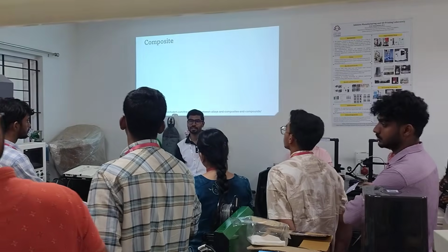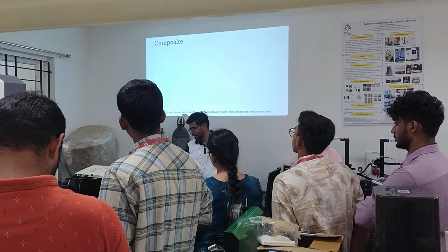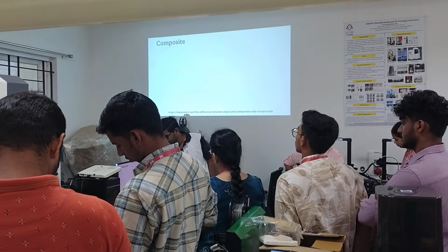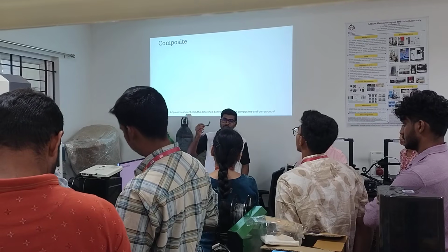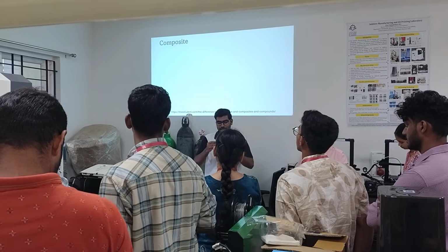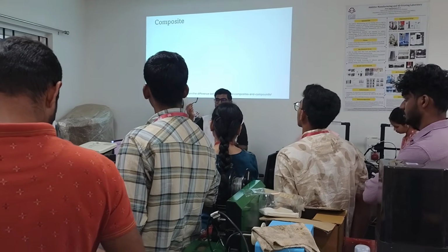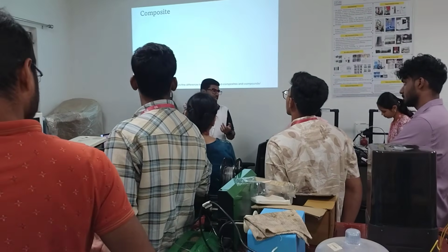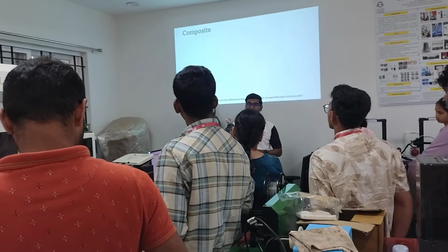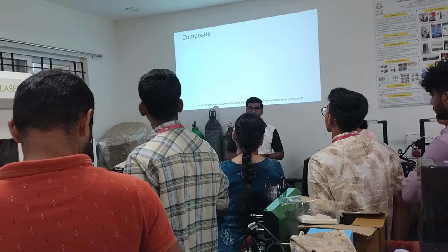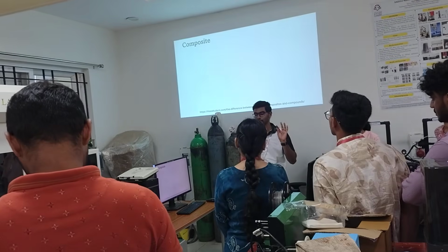So what actually is a composite? Yesterday, some of the participants were trying to print some composite materials. Composite PLA itself was infused with carbon fiber, and they tried to print a cube, and it came out somewhat like this. A cube was required, and we are getting this kind of part. It means there is a little bit of difficulty, even though carbon fiber is already infused into the PLA filament. That is one of the easiest methods, and still there is some mistake.